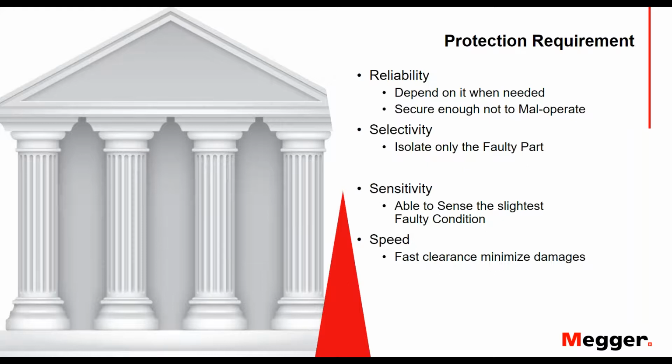Then we have sensitivity. It basically means that I should be able to sense and detect any fault, whether it's a huge fault or a small fault. And last but not least, speed, meaning a fast clearance of any fault type to minimize any damage or harm to your power system. Sometimes you have to compromise between speed and selectivity, or vice versa, to get an optimal performance from both.